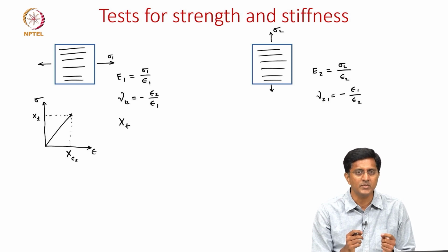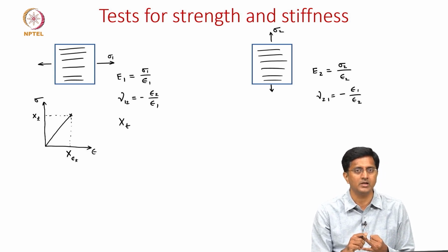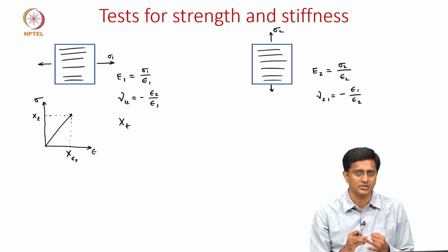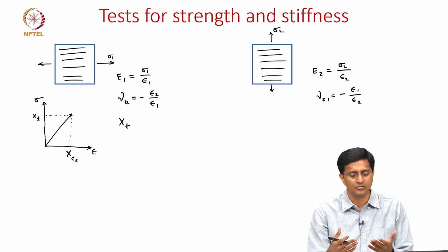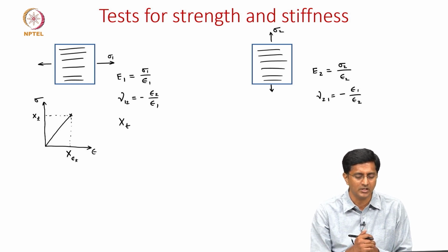But if there is a mismatch, then one should doubt the experiment, meaning the data collection might be wrong, or maybe it's also possible that the material is not linear elastic, because this relation between the Poisson ratios comes from linear elastic assumptions. So if that assumption is not valid, then from this experiment we can say that it is no more a linear elastic material,